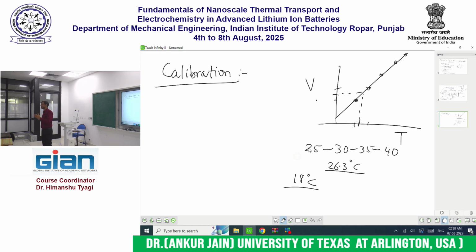Whereas, why did I start this process in the first place? I started this process in order to measure a temperature, right? So essentially the point is that in order to measure something, I need to calibrate, for which I need well-known sources of that thing itself. I need to have a body at 25 degrees Celsius, and then I need to have another body at 30 degrees Celsius and 35 and 40 and so on.